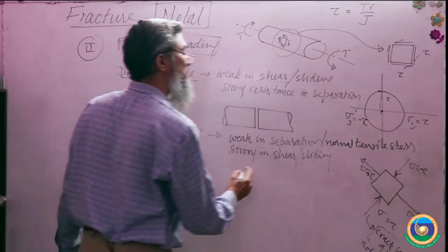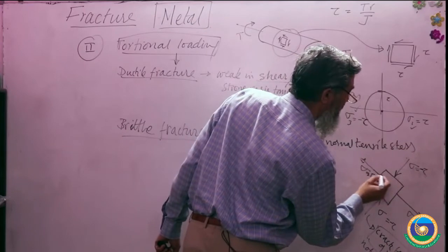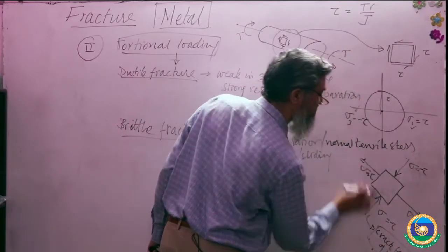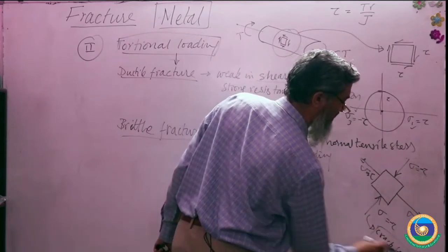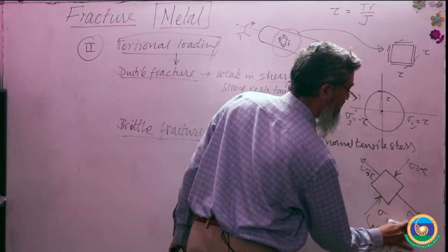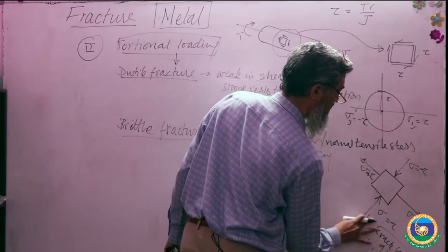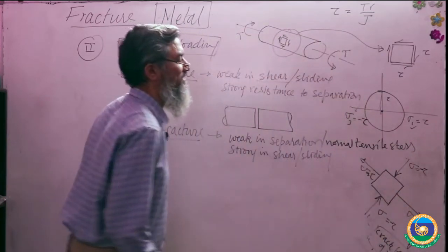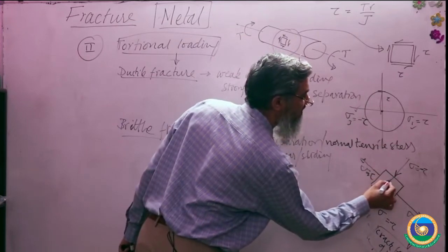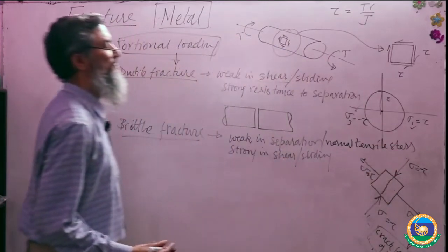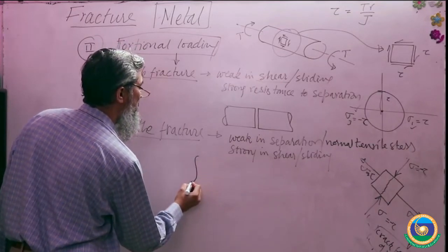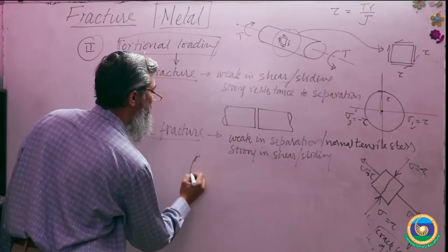So if you see here, because this is tensile, this is tensile, this will lead to crack formation and crack propagation, right? So you will find that at 45 degrees the crack will take place, and hence the helicoidal fracture takes place.